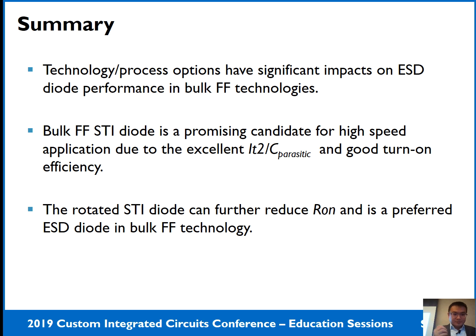So, to give a quick summary of the state-of-the-art bulk FinFET ESD performance. First, I already showed the technology or process option has a significant impact on ESD diode performance. Then the STI diode is a promising candidate for high-speed application because of the excellent It2 per parasitic capacitance.